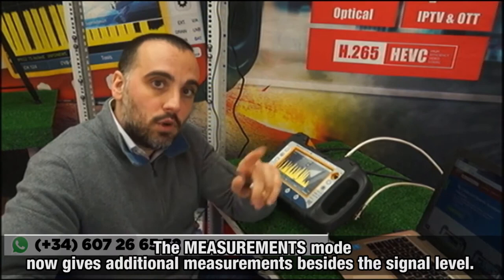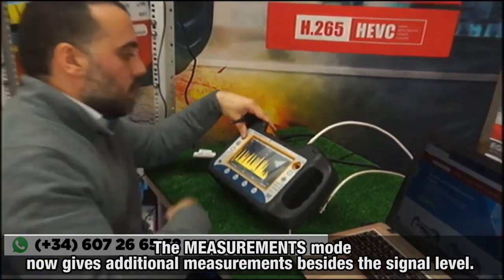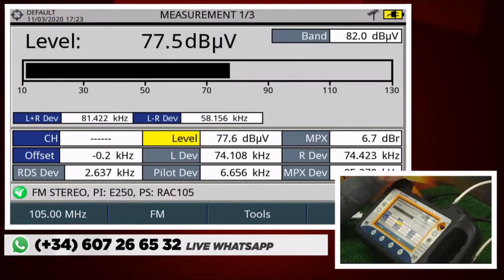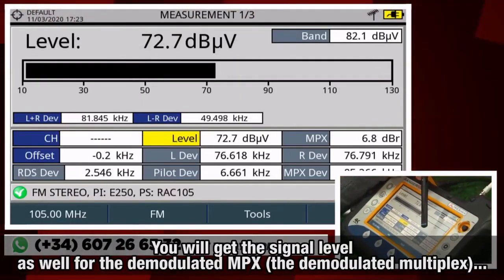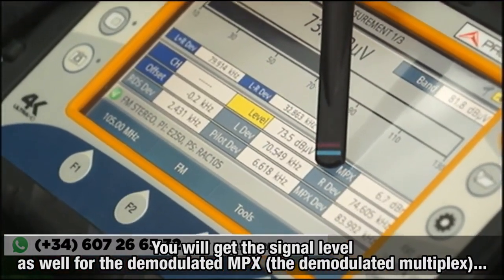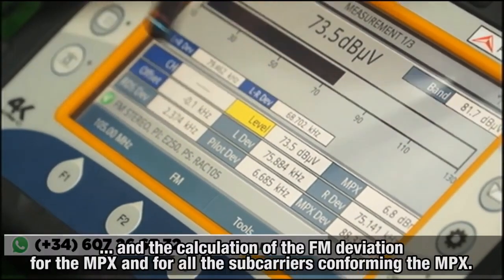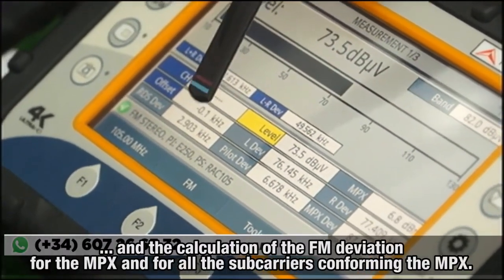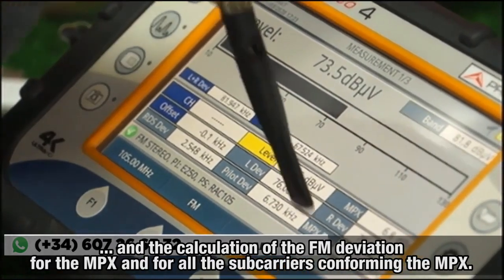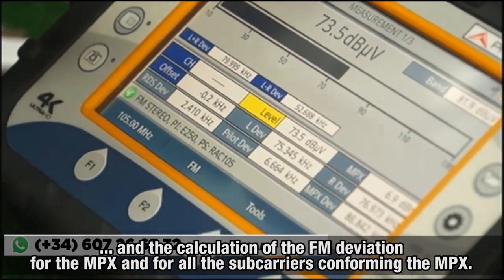First of all, if you go to the measurements mode, you will get some additional measurements besides the signal level. You will get the signal level for the demodulated MPX, the demodulated multiplex, and as well the calculation of the FM deviation for the MPX and for all the different subcarriers that form the MPX.